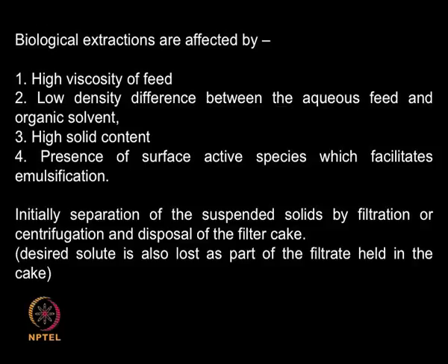There may be very low density difference between the aqueous feed and the organic solvent. So if the density difference is very low, then the separation time of the two streams into two different distinct layers is going to be time consuming. It will take a long time because most of the separation we assume is based on the difference in the densities.